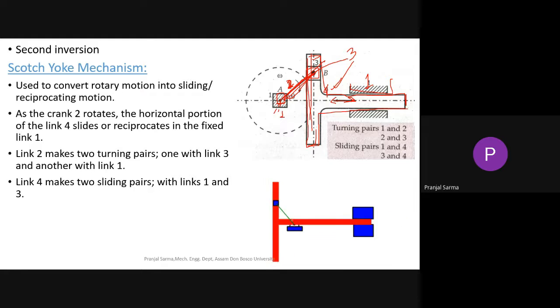Okay, so at the end point of this particular slider crank, we have got the slider. During the rotation motion of this crank, as they are connected, the slider is going to slide up and down on this head portion of the T. As it is moving from this side to this side, the locus of the crank is nothing but a kind of circle. So this side it will go up to the distance r, and that side it is coming up to the distance r. Yes, on both sides it is moving like this. Ultimately this is a circle it is tracing.